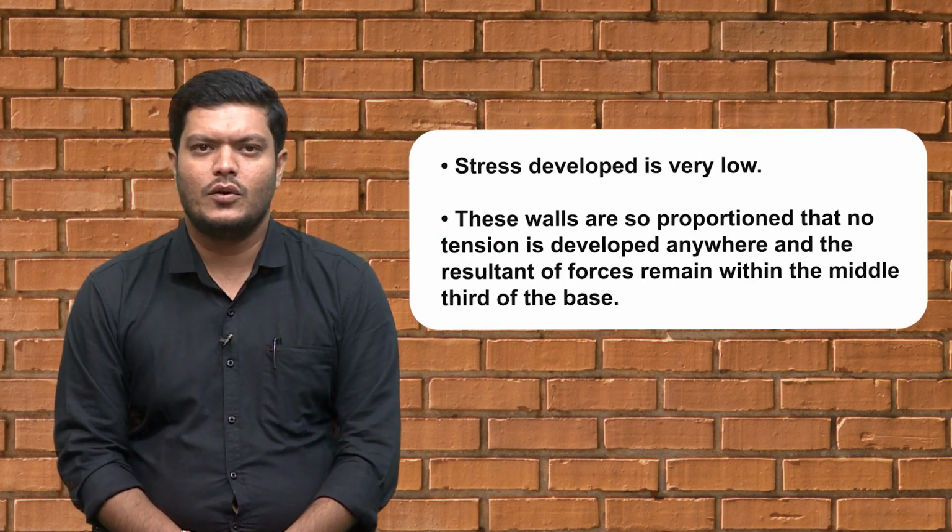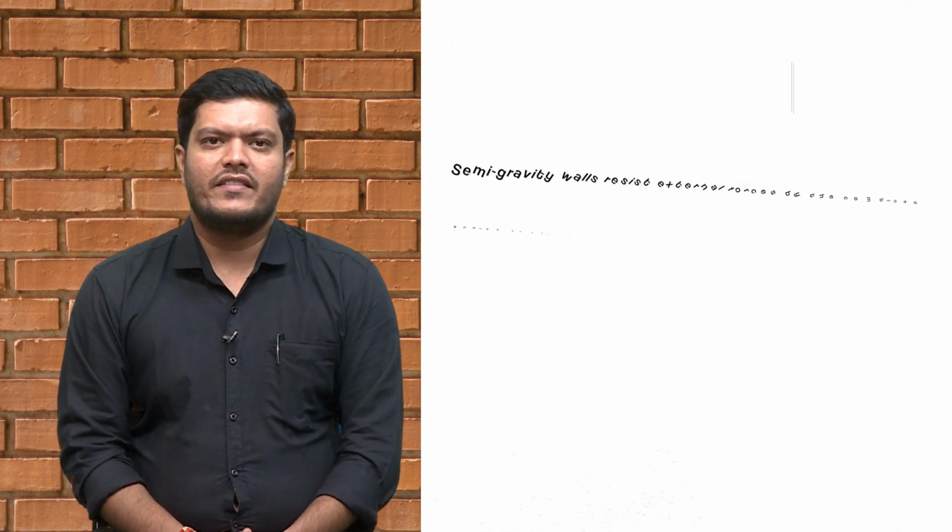Stress developed is very low. These walls are so proportioned that no tension is developed anywhere and the resultant forces remain within the middle third of the base. Semi-gravity walls.